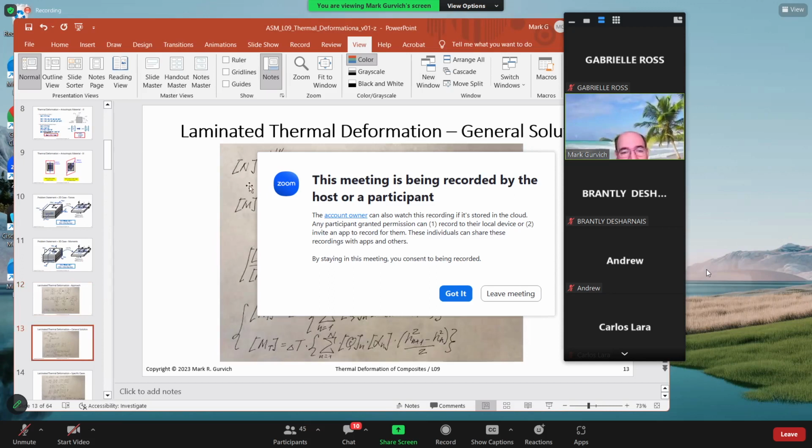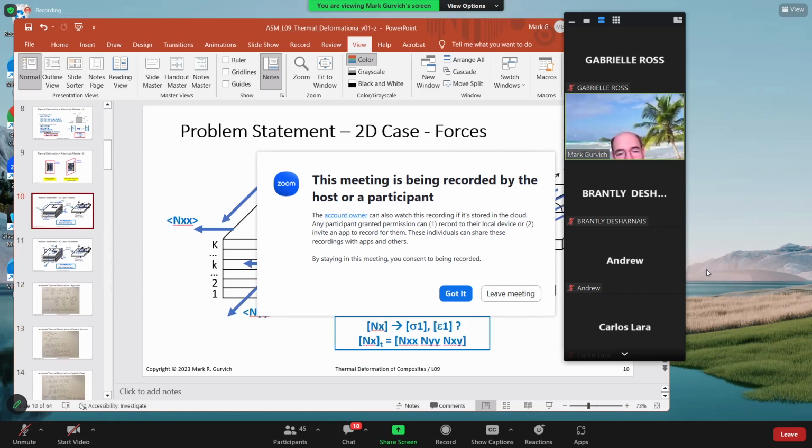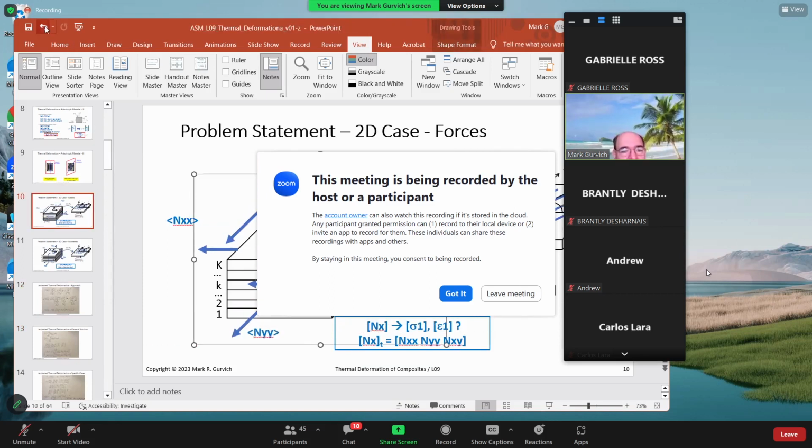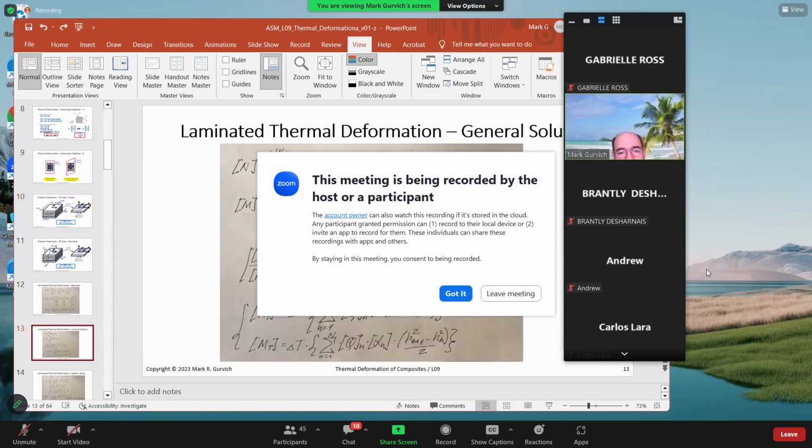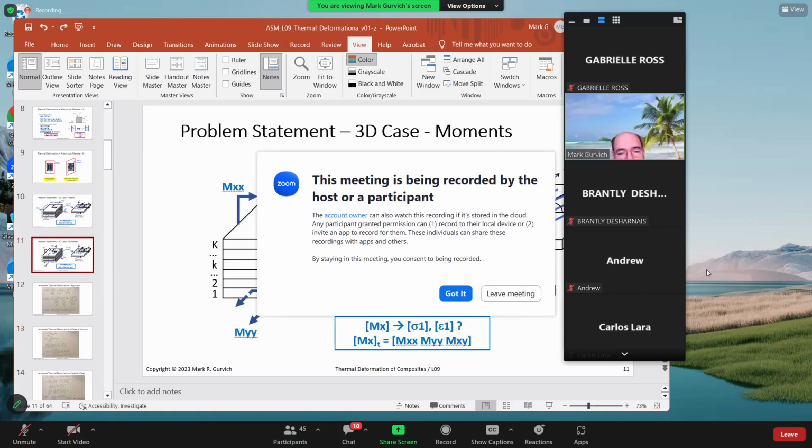What we're doing for equilibrium: if we sum everything through thickness, all our stresses should be integrated through thickness, through dz, and we will receive N. What is N? It's the combined force integrated through thickness. Similarly, if we integrate stress multiplied by Z position from the neutral position, we will also calculate all those moments.